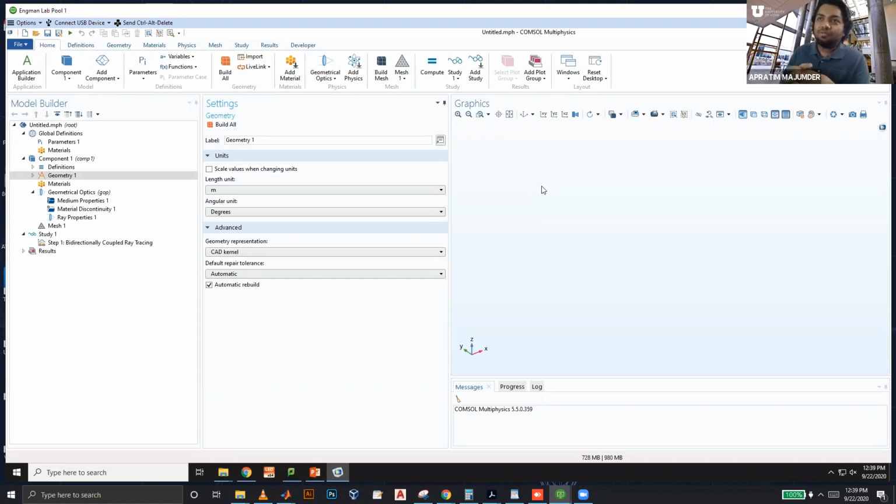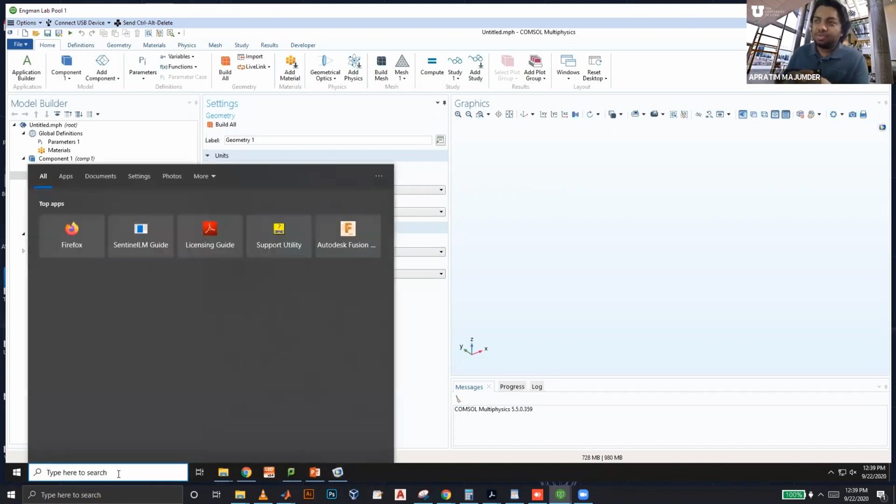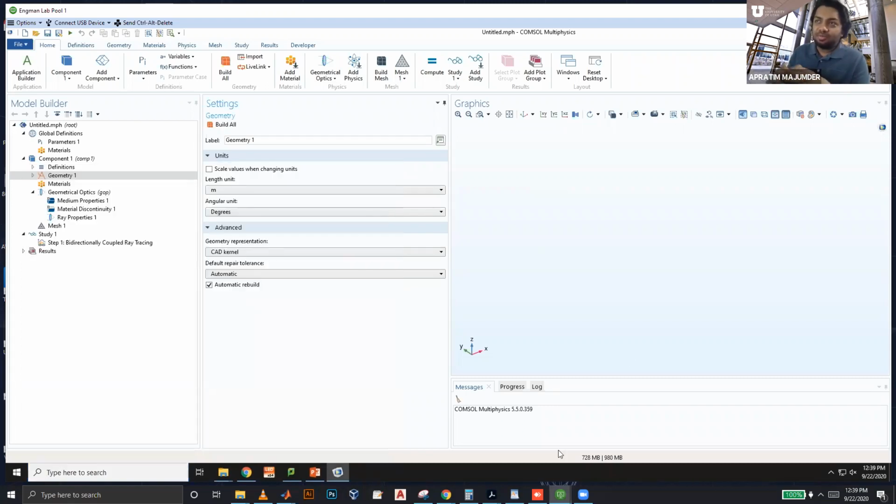So you can build a front end in MATLAB and then call Comsol on a server, and basically use your MATLAB program to continuously run Comsol in the background and move data back and forth. This is what I used to do when I was working on my doctoral project. So I used the Comsol with MATLAB server option, and you can explore that if you want, but that's not something that we're going to deal with today.